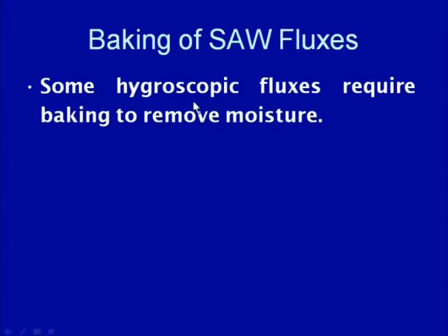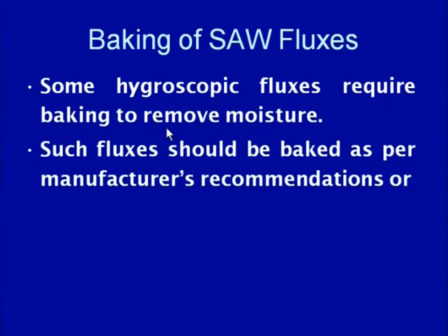As I said, some of these fluxes are hygroscopic in nature. Therefore, to avoid the presence of moisture in the fluxes, it is necessary that these are baked properly. Depending upon the type of the fluxes, the requirements and the manufacturer's recommendation, the fluxes are baked, and the hygroscopic fluxes are particularly baked for removing the moisture.